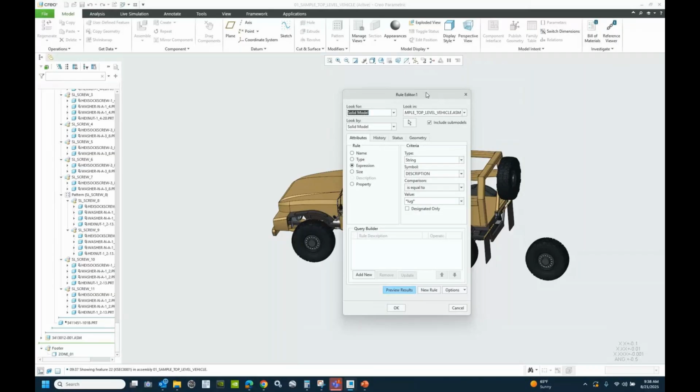For this, I'm going to say I want to create a selection by geometry. Here, the default for this rule is using a zone. I'm going to say inside the zone, which would be excluding, right? Because that was my condition. I'm going to use the zone that's available, zone 1, and I'm going to add that as my rule.